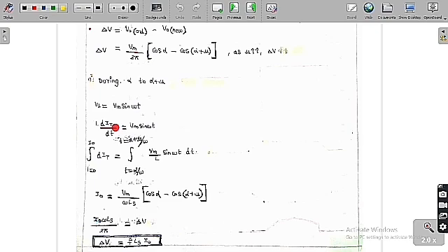The current through the inductor at that time is the thyristor current. Therefore di(t)/dt is equal to Vm sin omega t divided by L. So I take dt to one side and L downward, and we get di equal to Vm by L into sin omega t into dt.